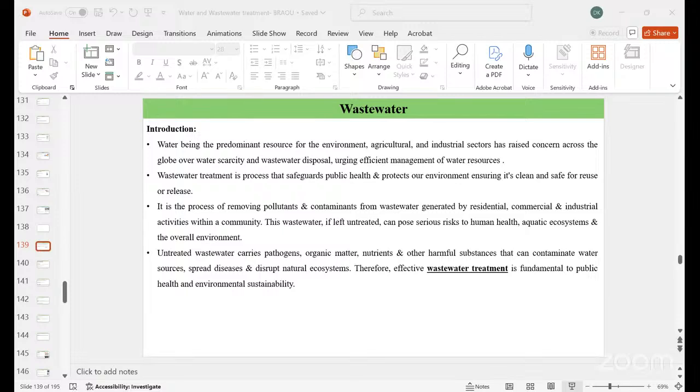And the color is an indicator of the presence of certain industrial waste or decaying organic matter, which is mainly measured by visual comparison with color standards or spectrophotometry. And odor can indicate the presence of decomposing organic matter, sulfides, and other specific pollutants which cause a foul smell. It can be measured by sensory analysis only.